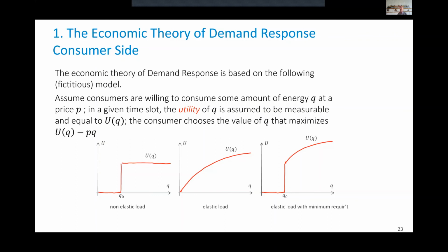In fact, what we did last week in the MPC problem, we didn't work in this way. There was not a utility function at every point in time, maximizing the utility minus cost. In contrast, we were putting a constraint that was saying, I want to minimize the cost of what I buy, subject to the constraint of running the house within bounds here. Those constraints were in the form of an MPC, which means the decision I take now at time t is not just based on an instantaneous maximization, but is based on an anticipation of what will happen in the future.